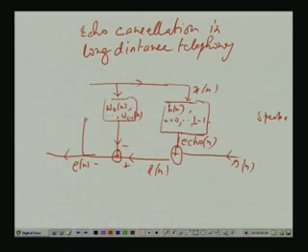And if I use the e(n), this is a symbol, to adjust these filter weights by the LMS algorithm, they are adjusted by the LMS algorithm by this e(n). What will happen? Then these filter weights, if everything else is done properly, will finally converge to, at least in the sense of mean, this h(n).